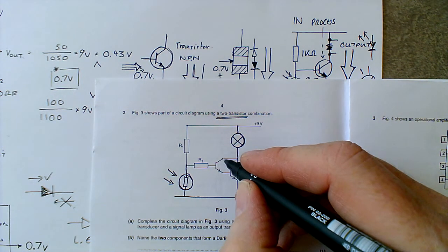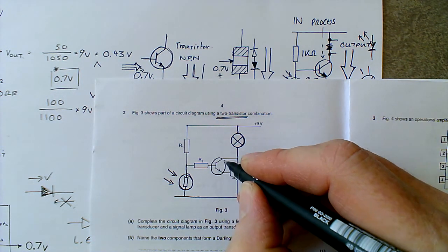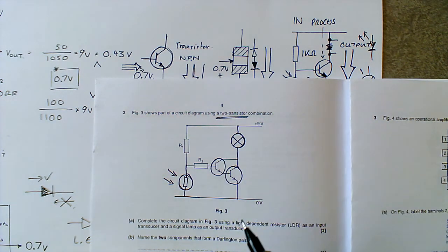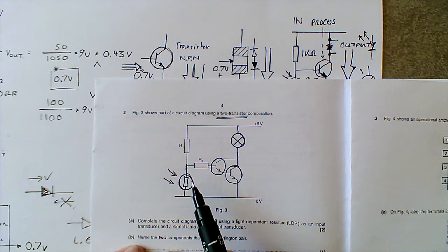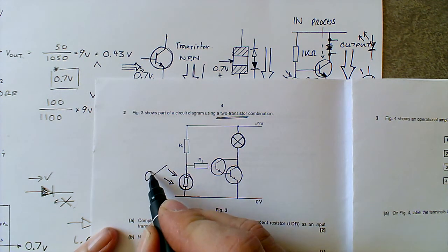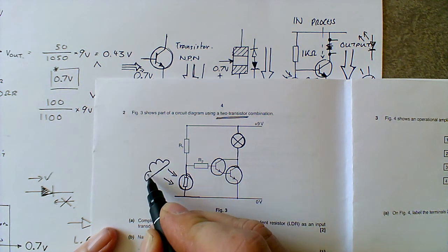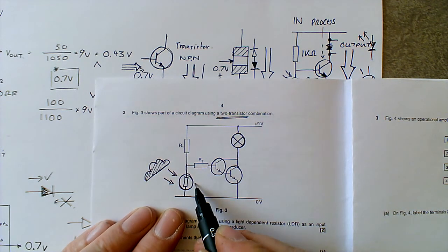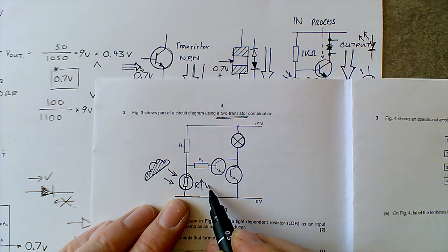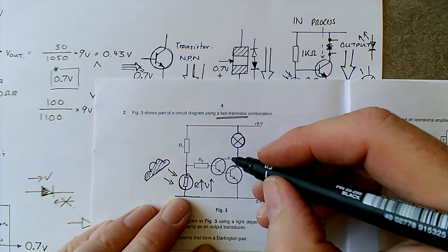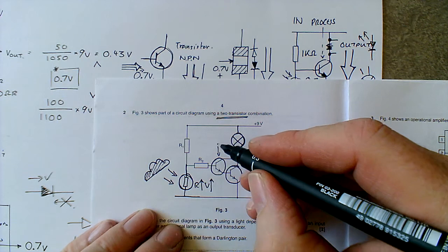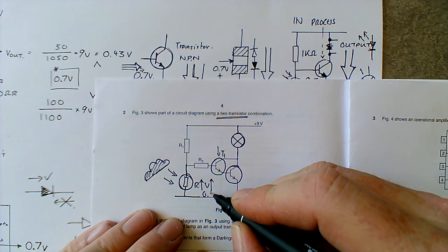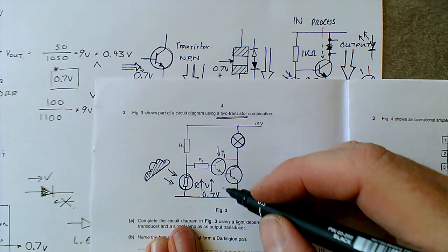Remembering, there's the light. Now we've got here, they haven't got their circles around them, but we've got 2 transistors. And actually, if we look at what happens, we can start to understand. So we know that if we have a cloud here, or if it goes dark, then the resistance here is going to increase, which means the voltage is going to increase, which means this transistor will switch on. Call that T1. So that will switch on at 0.7 volts.